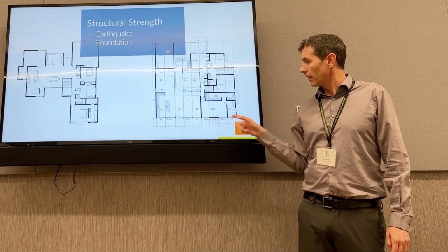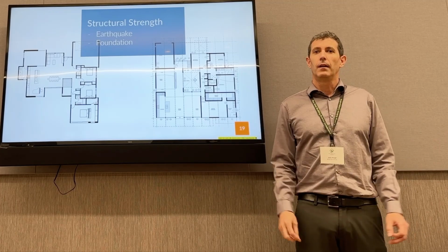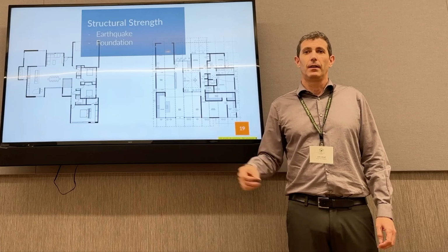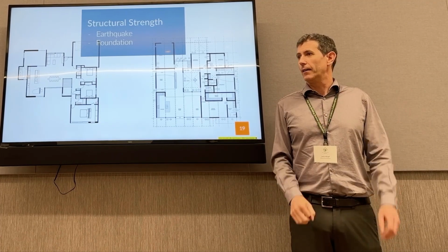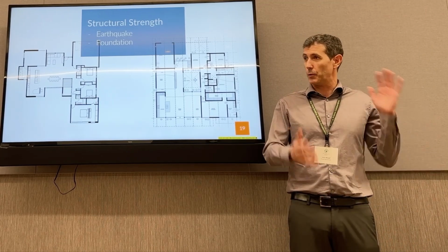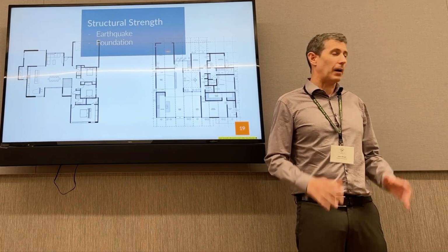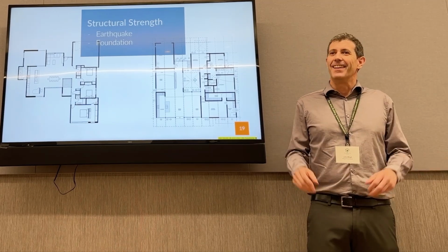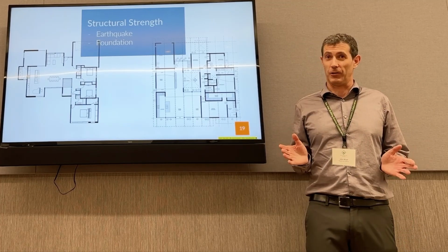Foundation of this house is like a 15-inch deep by 12-inch spread footing, and this is an Eichler home. There were 11,000 built. They're built all over the place, even in New York, but mostly in the Bay Area, ranging from up in Marin all the way down to San Jose and in between, the East Bay too. Well, the soil is different in all those places. They didn't bother to do a geotechnical investigation. They just have the same, and the architect drew the foundation. There was no structural engineer.